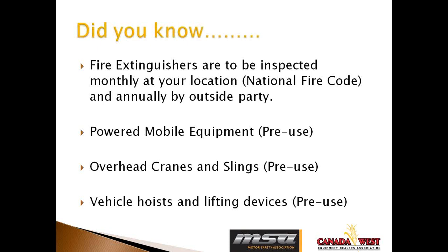You also want to do pre-shift or pre-use inspections of your powered mobile equipment, overhead cranes and slings, and vehicle hoists and lifting devices. Those are requirements in Saskatchewan. A lot of times, for example, the operator's manual of the powered mobile equipment may have a pre-shift inspection template. If not, we would be able to help you locate one, or you may be able to generate your own that's specific to the machine or item that you're inspecting.